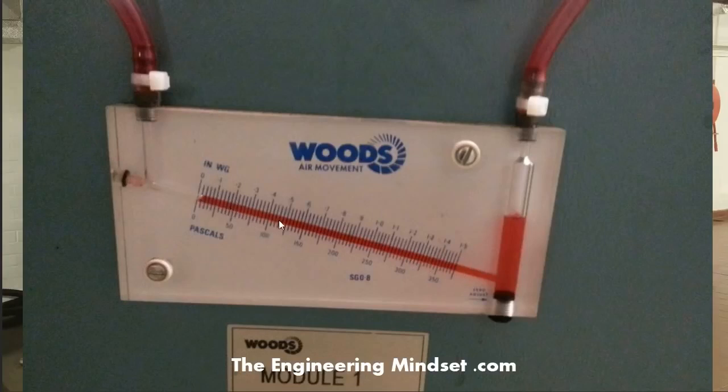This will change as the pressure increases across there. There's no pressure drop at the moment, but as the filter becomes more and more dirty, the reading becomes greater and greater. This is measuring the difference between the intake and the suction side across the filter, and that's how you know how dirty it is.